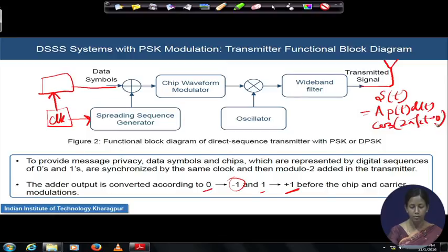The signal we have generated earlier is getting transmitted. But before that, we have to pass it through a power amplifier to boost up the power level, because the signal is expected to traverse a long distance over the wireless communication channel, and the wideband filter is utilized to cut out the unwanted signal portion of the spectrum out of the band of our interest.